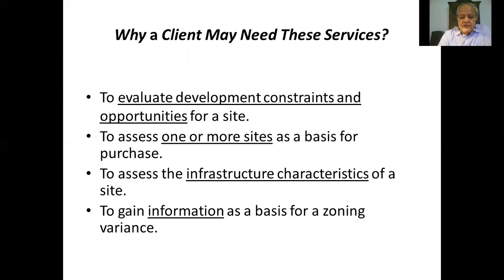So your service will be to evaluate the site and develop the constraints and opportunities. The client might have more than one site, so they ask you to help them select the appropriate site. So you need to think about the infrastructure characteristics and information about the zoning regulations and the number of floors, the FAR, the building footprint allowed.